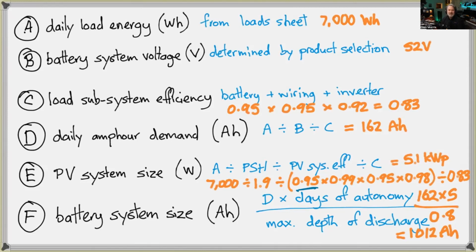It's one small advantage of living in a cold place, your panels actually produce more power. So go Tasmania, Chris. They produce more power. They just love the cold, by the way. They really love it. So in this case, I've chosen winter. The ambient temperature is low, and I'm only losing 5% of my power.